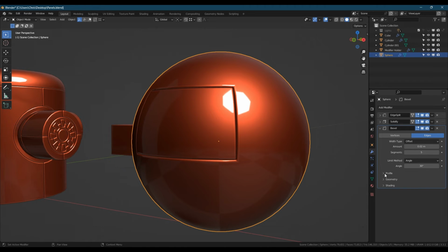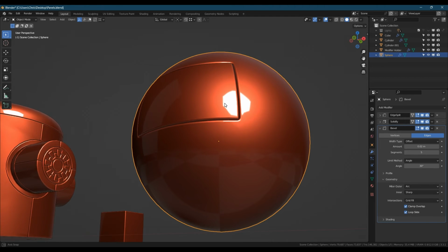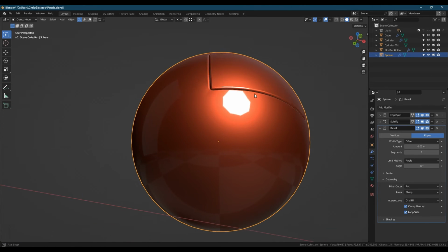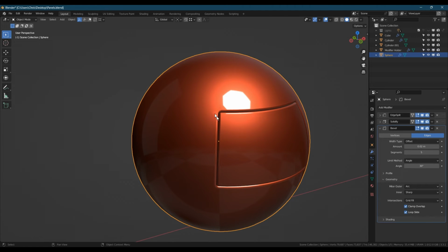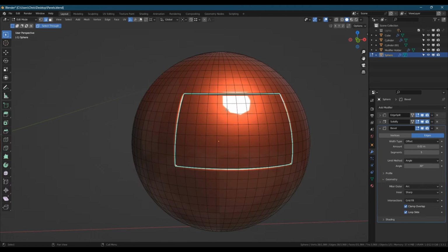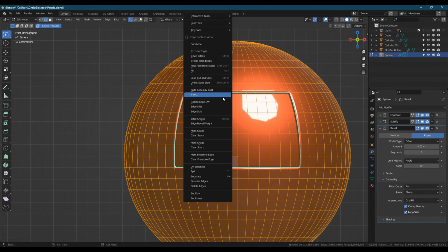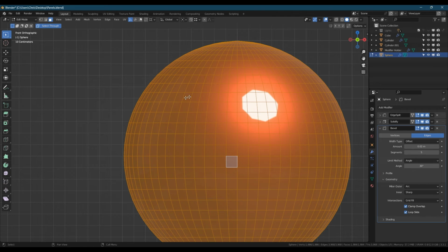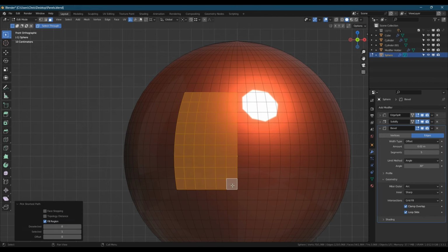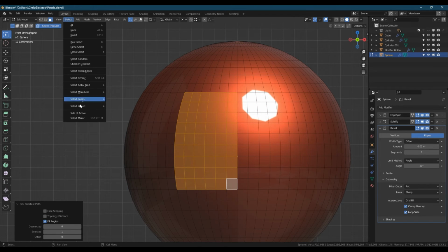If we look at the bevel modifier's geometry tab, specifically the miter outer dropdown, here you can change it from sharp to arc, and what this does is change the corners of the bevel to round like the internal ones. I do think this looks a lot better in most cases, but you'll notice when you use it that there's some shading issues now coming from those corners. The simple fix for this, as I said before, is just to inset it before, and this confines the shading issue to that ring of faces where it's more or less unnoticeable.